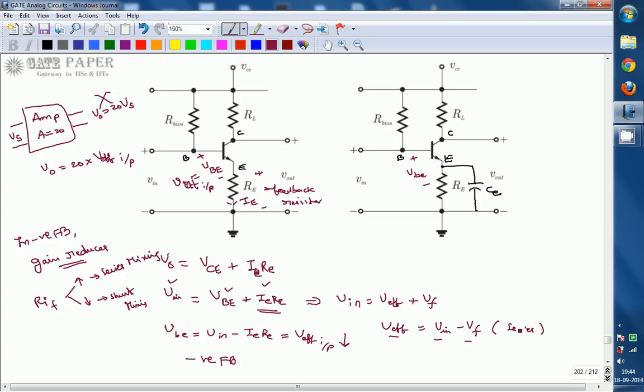Since all the input parameters, that is the input parameter, feedback parameter and effective input parameter, are of voltage type, voltages get either added or subtracted if they are connected in series. So the type of mixing used is treated as series mixing. In series mixing, input impedance with feedback increases. So if RE is considered, feedback is present, which implies gain reduces and input impedance increases.